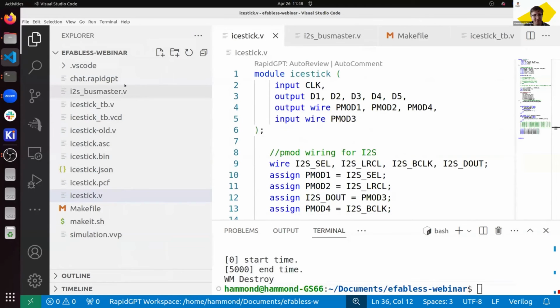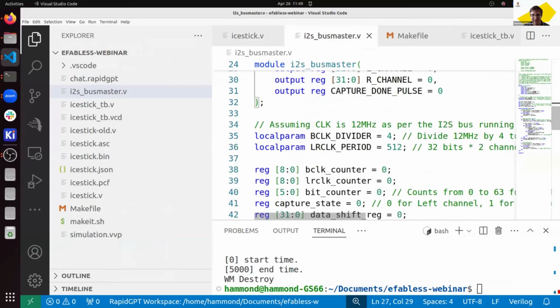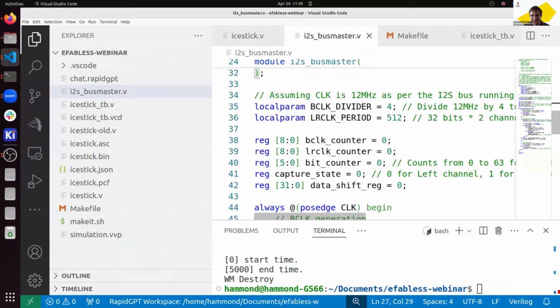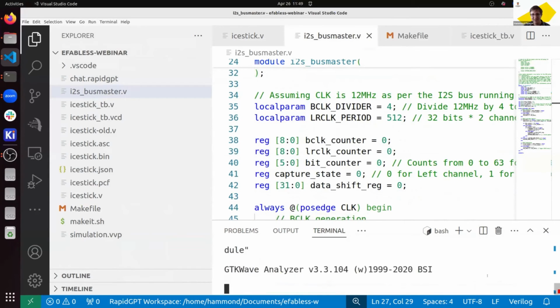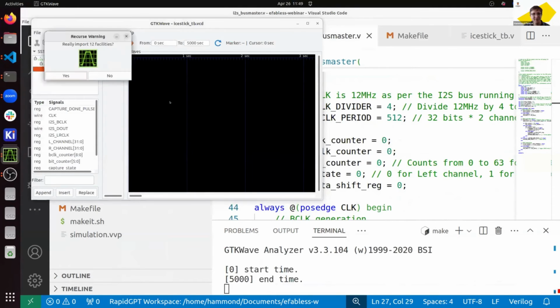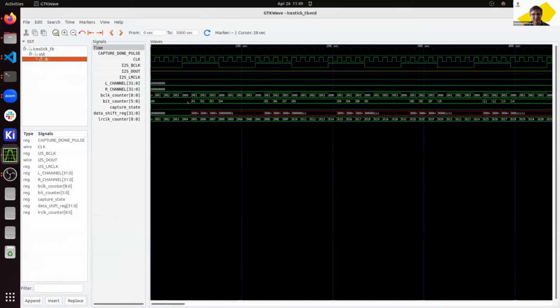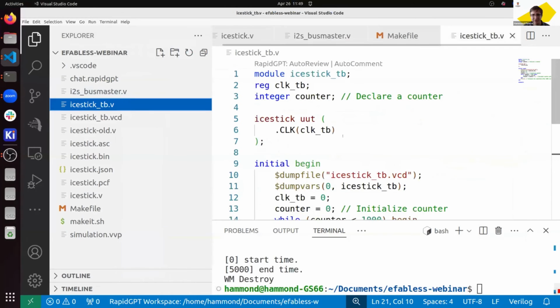So if I head back to the bus master, where it's made regs, I'm just going to drop in this nasty hack to set everything to be 0 to begin with. And what that will do, of course, is give it those initial values that it needs to... Oh, some of them it did. Okay. And what that should do is give us the initial conditions. Okay, no, it's still not 100% happy here. It looks like the data out signal isn't being set properly. That's my test bench. That's at fault.